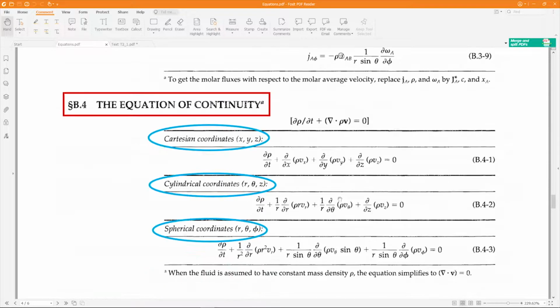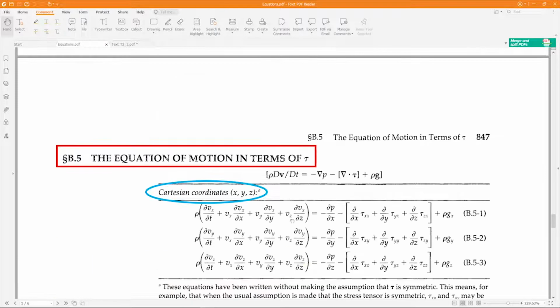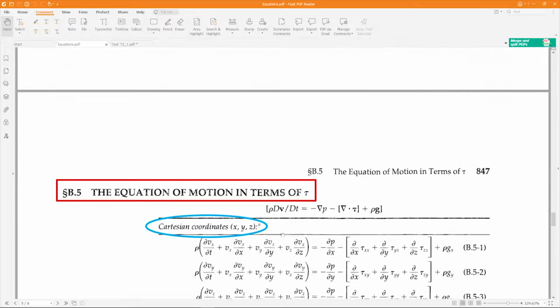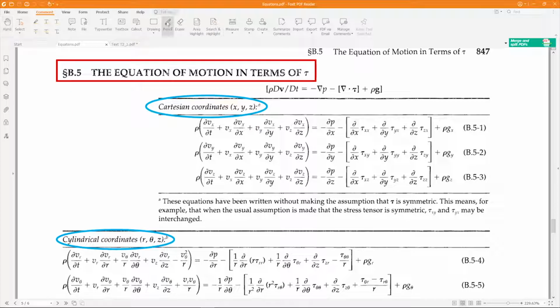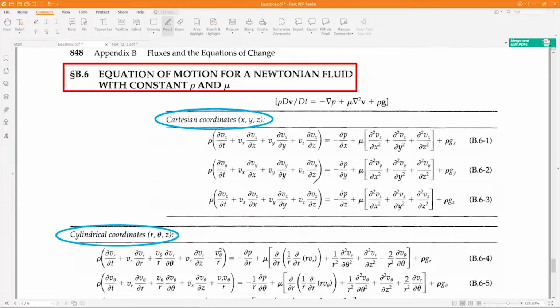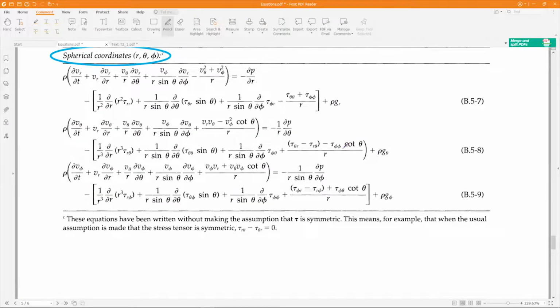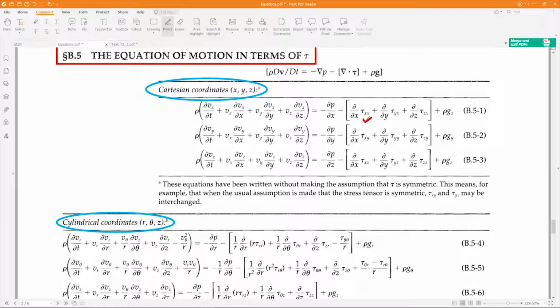So you can directly solve for the velocity profile, or you can use the shear stress formula. See, in this formula we have shear stress. Or you can directly use the velocity equation to get the velocity profile. But suppose in the problem it is asked to find the shear stress profile. Then it will be better to integrate this equation in terms of shear stress.